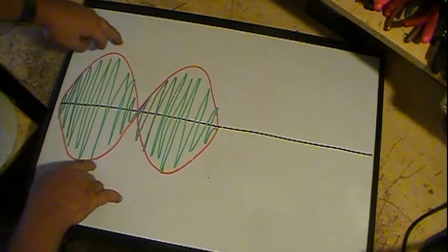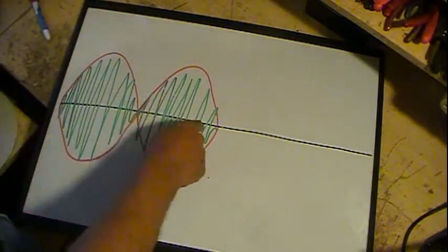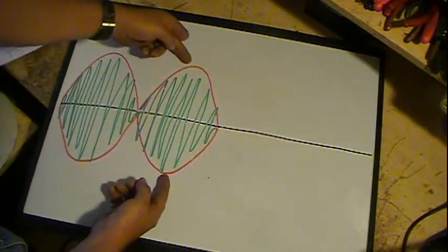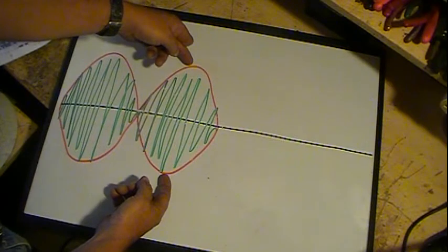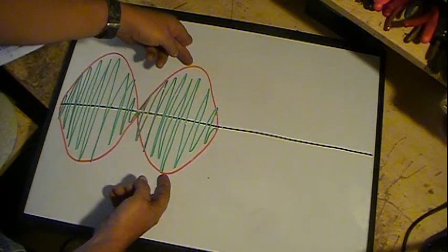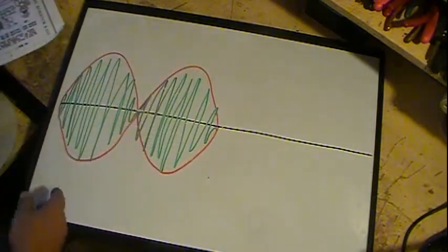The thing is, these are mirrored images of each other. Now, if I was to take this and try to feed it into any type of coil or transformer, run it through the audio amplifier section and out to the audio output transformer and out to the speaker, what would end up happening is these two, since they're 180 degrees out of phase and identical and mirrored, would actually go to zero. You would have absolutely nothing.